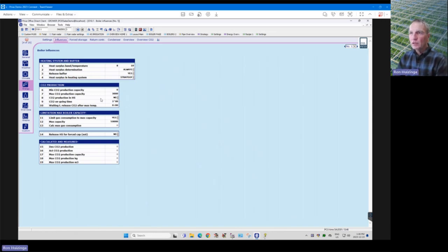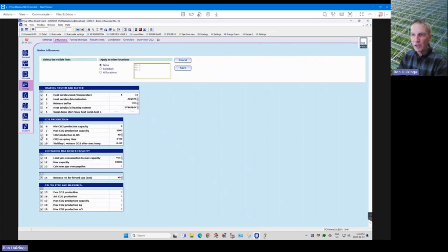The settings up here, basically lines 1 through 4, typically you wouldn't touch these lines, because once they're set up by the dealer, they should be working fine. So this is the only basic one that customers are usually touching. CO2 production high speed, again, is one of these lines for those 2-speed fans we used to have, so we can actually get rid of that.